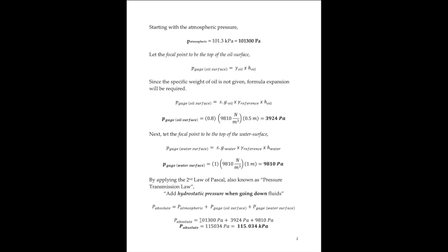Finally, adding 101,300 Pascal plus 3,924 Pascal plus 9,810 Pascal gives us the absolute pressure as 115,034 Pascal, or 115.034 kilopascal.